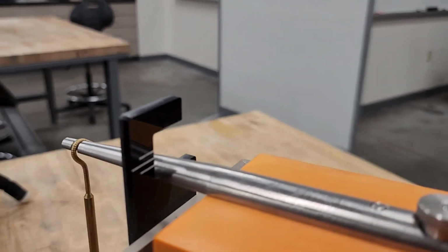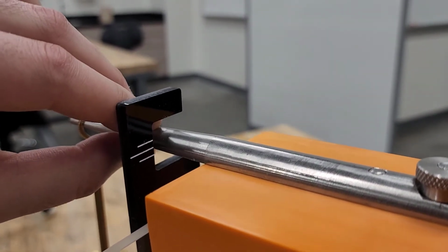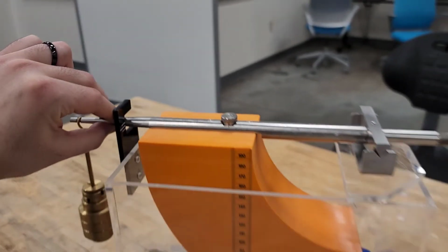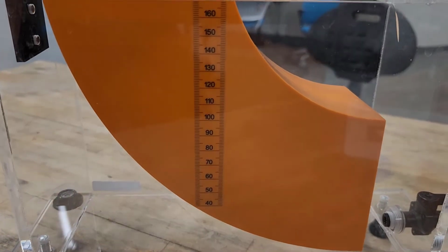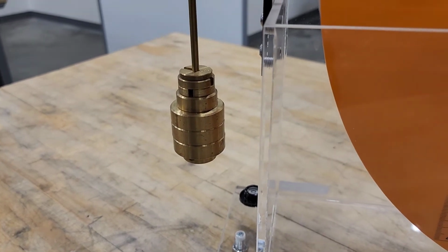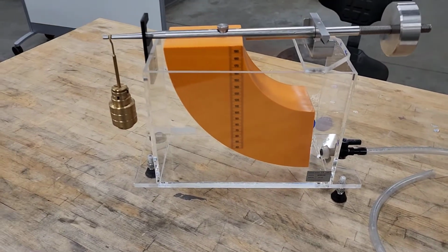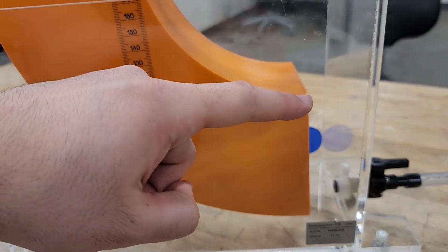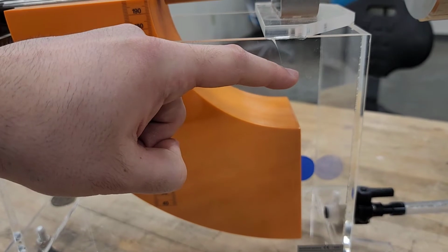How do I know if it's balanced? You can see that there are three lines over here. Whenever the bottom edge of this lever is parallel to the middle line, you know that the system is level, and you go ahead and read the depth of immersion, and also read the amount of weight, the mass that you have on top of your weight pan. You're going to repeat this process for partially submerged, whenever the depth of water is below this point, and also fully submerged, whenever the depth of water is higher than this.